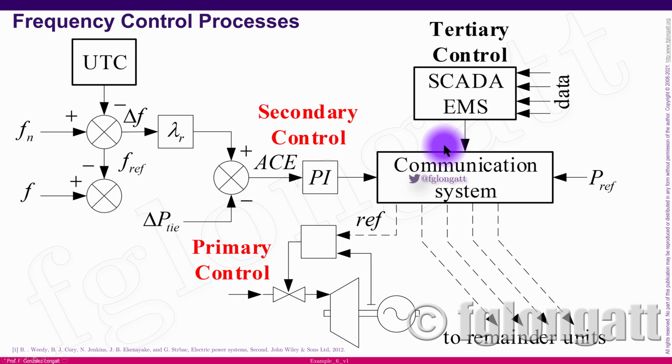And here in this slide, you can see the two different controls, okay? Here we have the synchronous generator. Inside we have the inertia response, and here we have the governor. This control loop is basically acting on the prime mover of this synchronous generator, and this is the primary frequency control. The reference is coming via a telecommunication system, and in that telecommunication system we can define those references, okay?